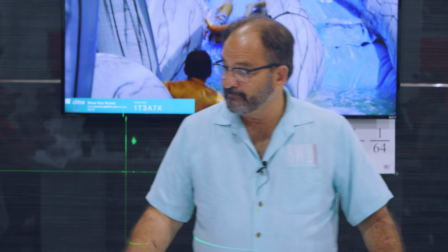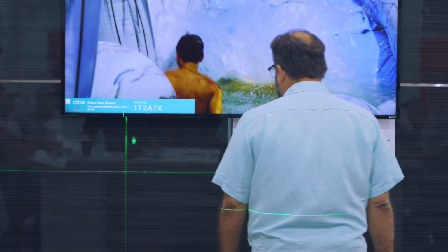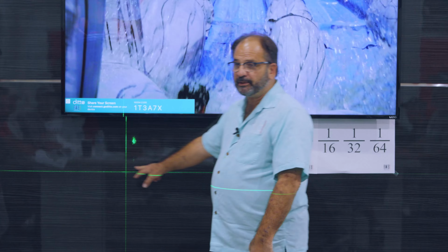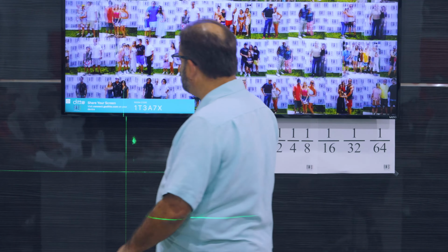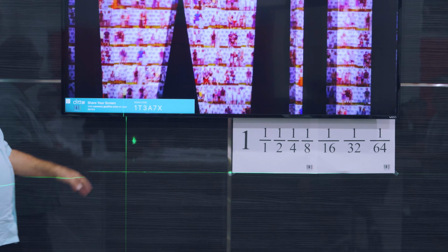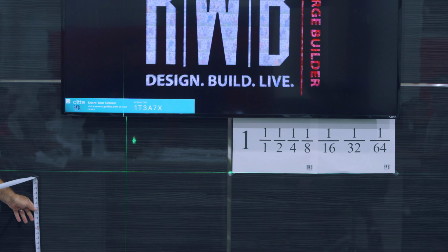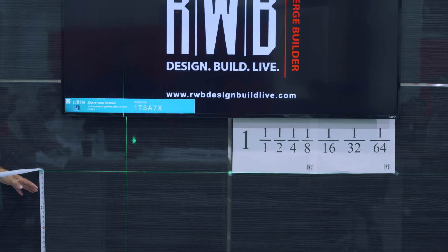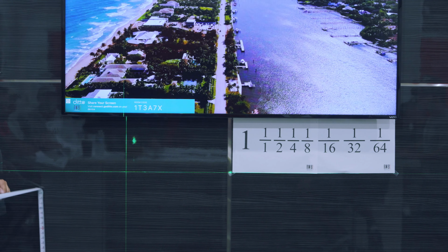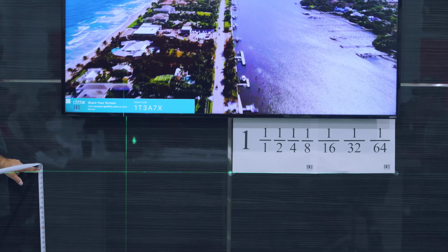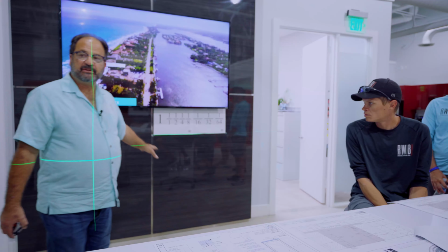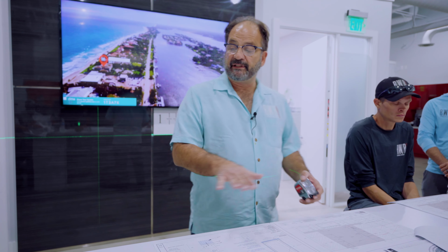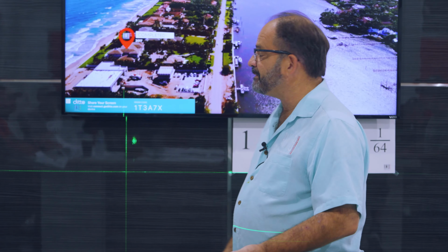We also talked last week about benchmark. Okay, so for example, you go into a room, you have an elevation on a wall, benchmark at a certain height, okay? You know from this, that's level. You don't know if your floor is level or not. If you measure off the floor and your floor is going like this, the dimension is going to change depending on where in the floor you go. So you know the point you're going to set your floor at. You have your elevation, okay? From that, you got your point.